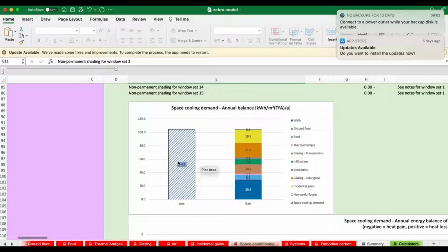We've also other U values we can treat as a U value of the wall, of the roof, and the glazing transmission. So let's go and instigate some changes based on those things and see if we can bring this 104.5 of energy demand down. So, and this shows you, I think, how rapid you can model design alternatives and play games when you're in a design meeting as a group of people or in a studio lesson, and seeing what happens.